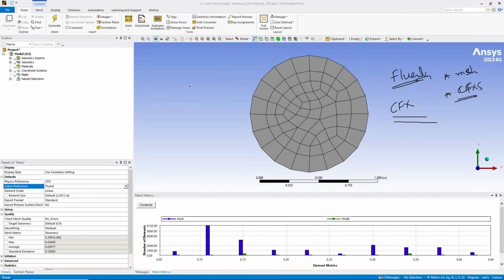But now, for example, if you want to specify the angle of attack, in Fluent we just give the cos and sin theta components. But in CFX, actually, we have to define those functions first. Either by defining the functions, then we put the values for the angle of attack, or we have to define a new coordinate system in CFX.